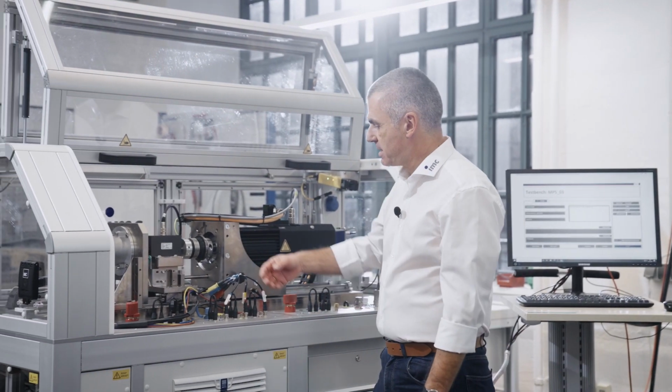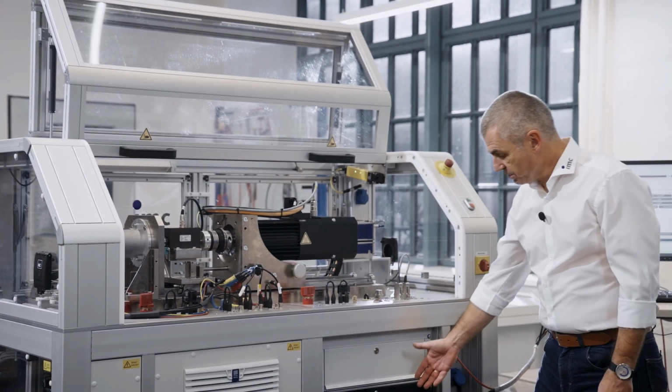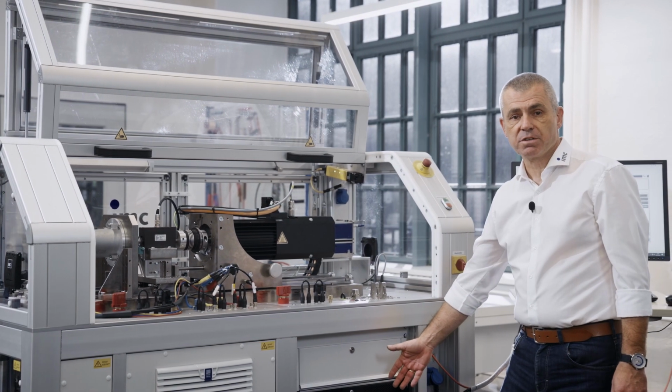Hello and welcome. In this video, we will show you the process and evaluation of the static flux table test type. This test provides information about the efficiency and the losses of the motor and helps to match the controller better to the motor. This test is a so-called active test, which means that the motor is energized, getting the power out of the inbuilt industrial converter of the test bench.